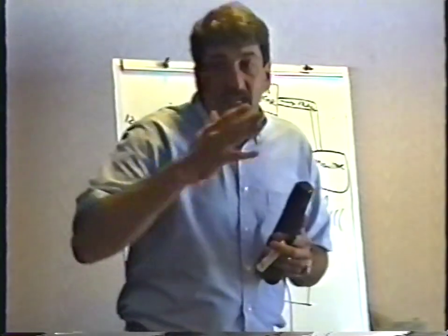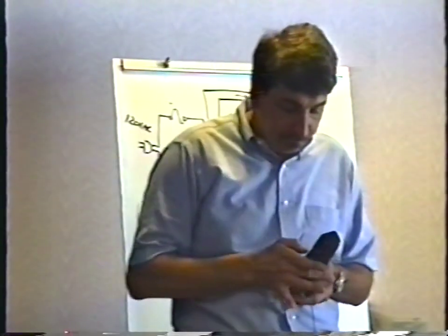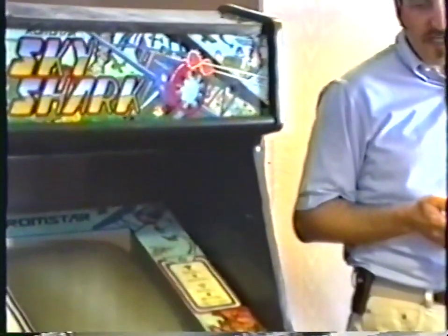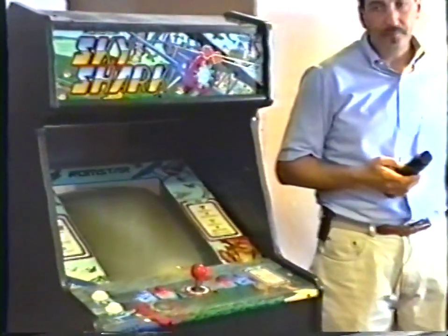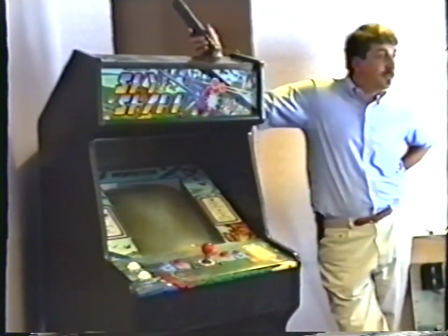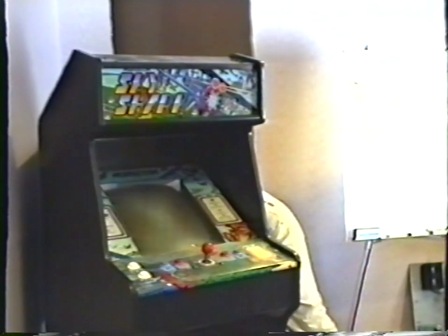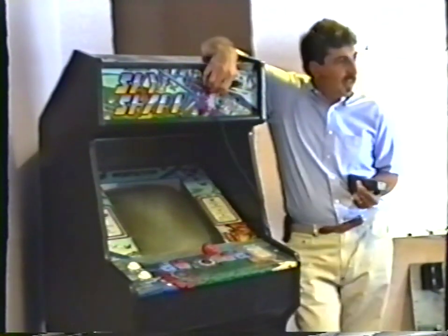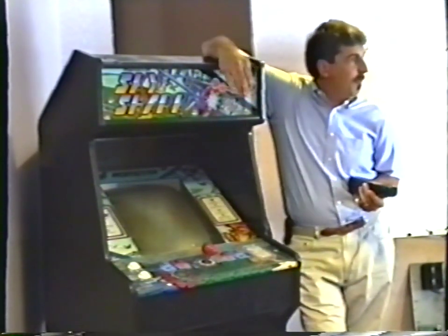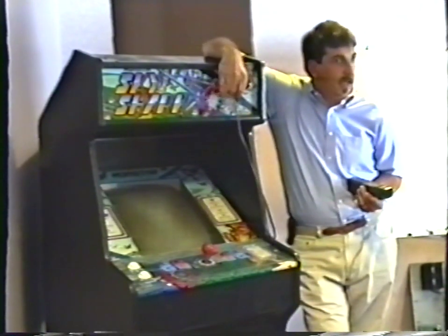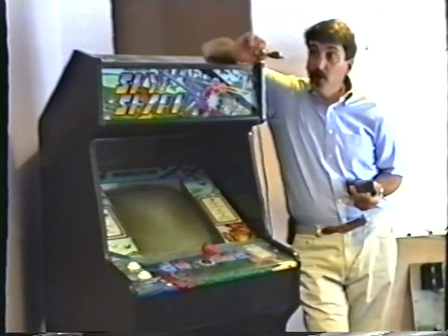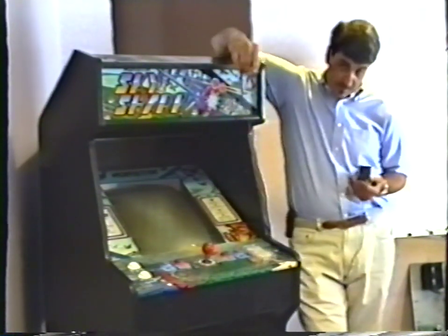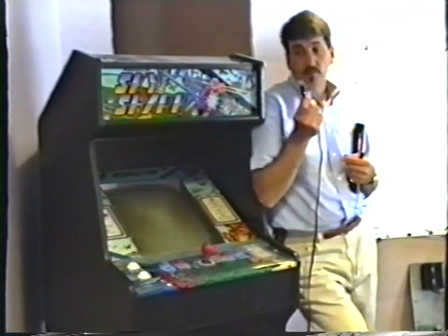Well, let's say you get to the game and here's a typical problem with a game. You plug the game in. In this particular game, it does nothing. In this particular instance, this game does absolutely nothing when I plug it in. When I plug in the main power cord here into the wall, no lights, the marquee light doesn't light up, it doesn't make any game sounds, it's completely dead. The first thing you want to do is to check the power cord. This is obviously pretty simple, and I'm sure that you've had this problem many times. And in this case, this is what's wrong with it.